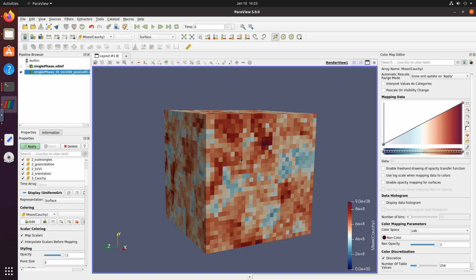This is a very good question. DAMASK does not have any idea about dimensions. It is just the number of grains and the number of grid points it has to solve, every grain, load and so on. Right. So if the number of grains and their shapes and their volume percent remains the same, but we just increase the resolution, right? So instead of 30 by 30 by 30, we define, for example, 100 by 100 by 100 or 300 by 300 by 300.